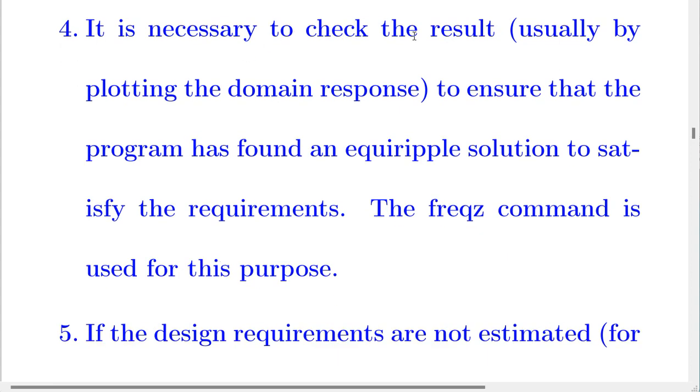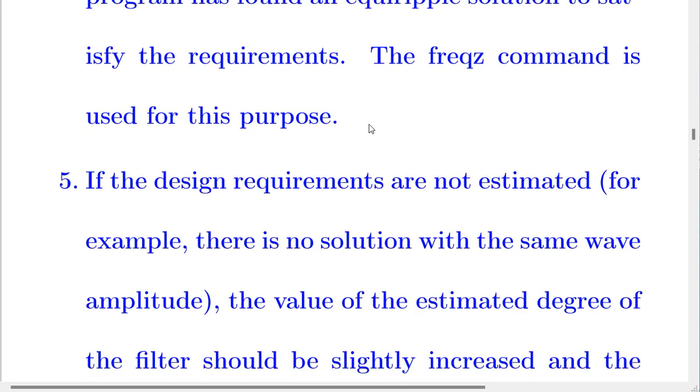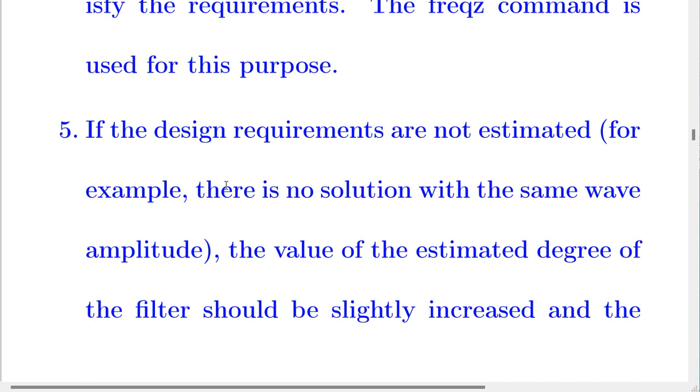It is necessary to check the result, usually by plotting the magnitude response, to ensure that the program has found an equiripple solution that satisfies the requirements. The freqz command is used for this purpose, or any method you are familiar with.